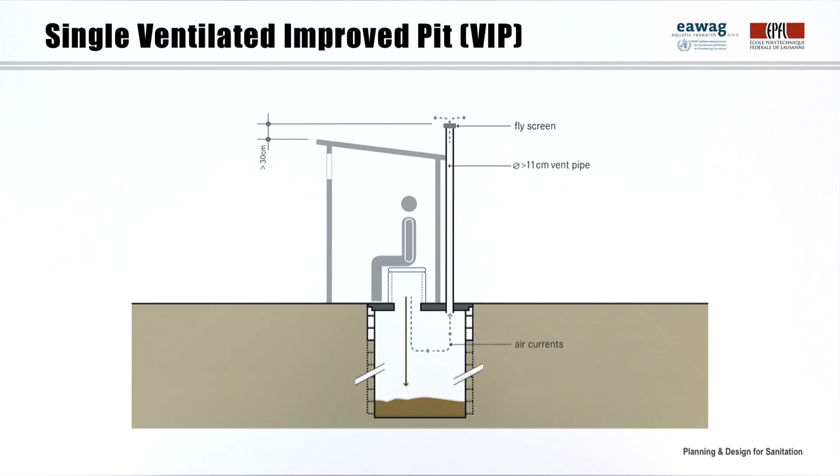the pit. Besides removing odors, another beneficial effect is that flies that hatch in the pit are attracted to the light at the top of the ventilation pipe. With a semi-dark superstructure, flies fly toward the light in the pipe. A fly screen or mesh at the top of the pipe traps them and prevents them from escaping. The attraction for flies from the outside is also minimized because odors are allowed to escape.